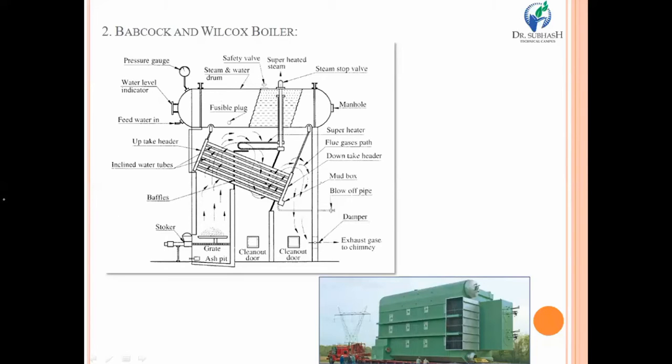This is a very important and essential part of any boiler, because it stores both the input quantity, water, and the output quantity, steam. Now, exactly on the top surface of the water and steam drum, or we can say the shell of the boiler, there is the superheated steam outlet. These pipes provide the superheated condition of steam, and this is produced by using the superheater over here.